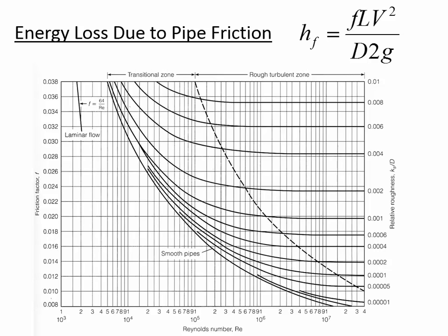And this diagram that's on the screen here is called a Moody diagram. Kind of a funny name, but it's a diagram that's a graphical solution for the F value based on flow conditions. And actually, when you get into water resources engineering, you're going to see a lot of this diagram. There are some equations that you can use as a substitute for the graphical approach. But let me just talk through this diagram so that you understand more on what it's representing.